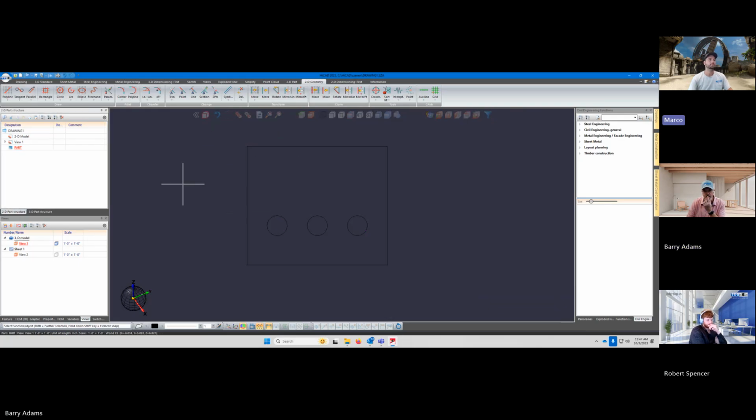Okay, so try this again. Circle. So if I want to reference that, would I hit the center point? Remember, you want to reference from a point. Remember how we had a command where we could give it a reference point and then an XY coordinate from that, and it would reference from a certain point.